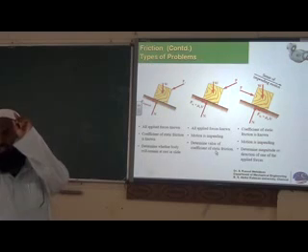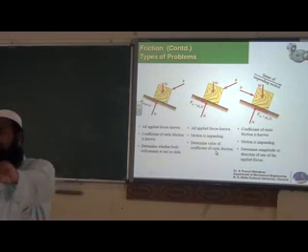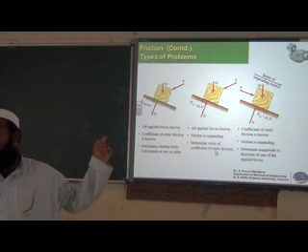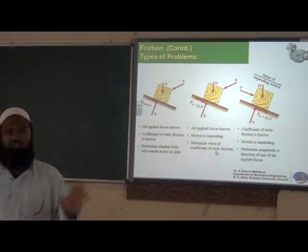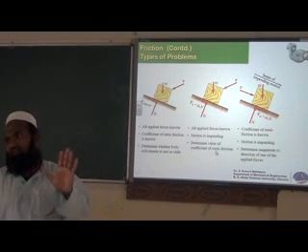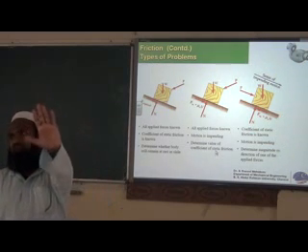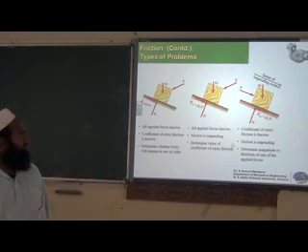So if they say motion begins, it is still not moving; it tried to move. So at that point, you will have only static friction, and we have to find out the coefficient of static friction. If they say motion begins, it means it just tends to move. So still it is in a static condition. Fm reaches the maximum value. The applied force is equivalent to the maximum friction force.